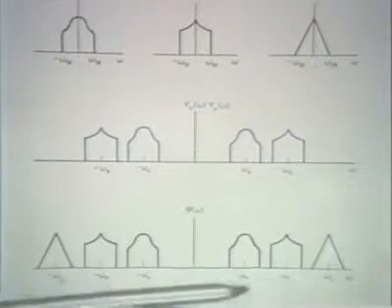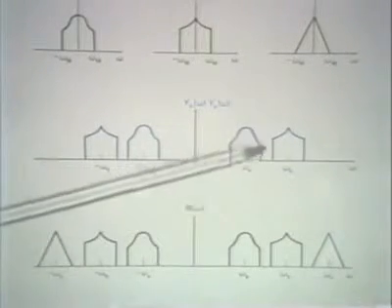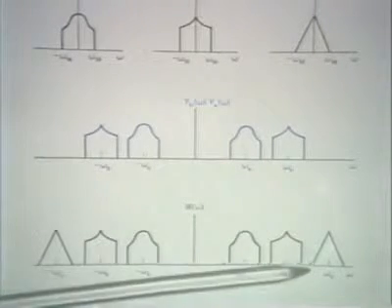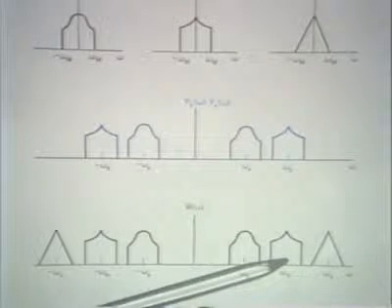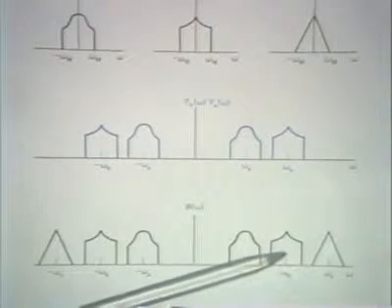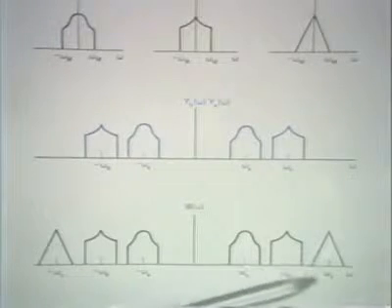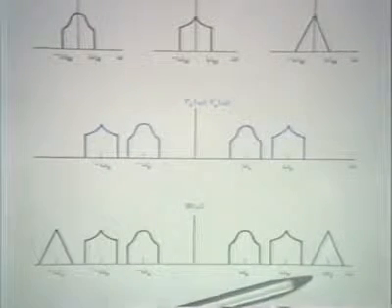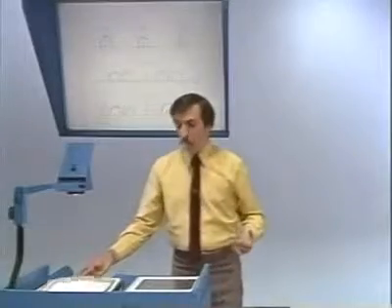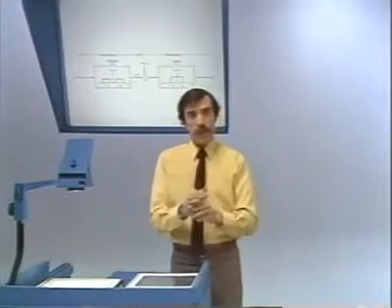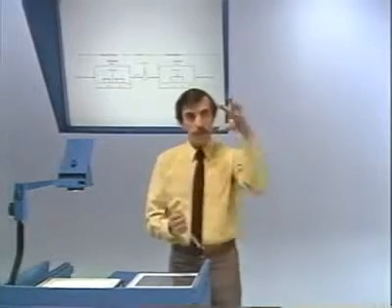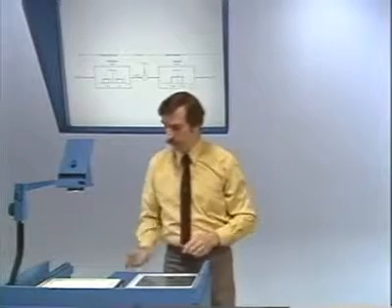And as you can see, essentially, by doing appropriate bandpass filtering, we can pull out whatever part of the spectrum we choose to, and then demodulate that in the appropriate way. And of course, we can do this not just with 3 signals, but perhaps with tens or hundreds of signals. So that's a process that is typically referred to as multiplexing. And as I've described it here, it's referred to as frequency division multiplexing. That is, dividing the frequency band into cells and plunking different signals into each one of those.